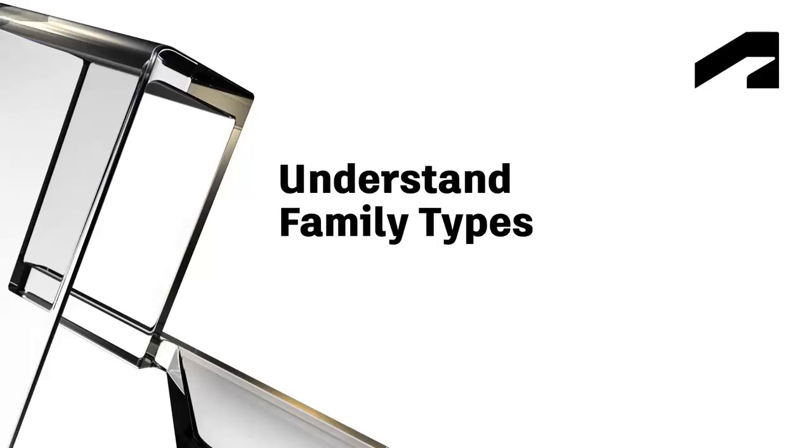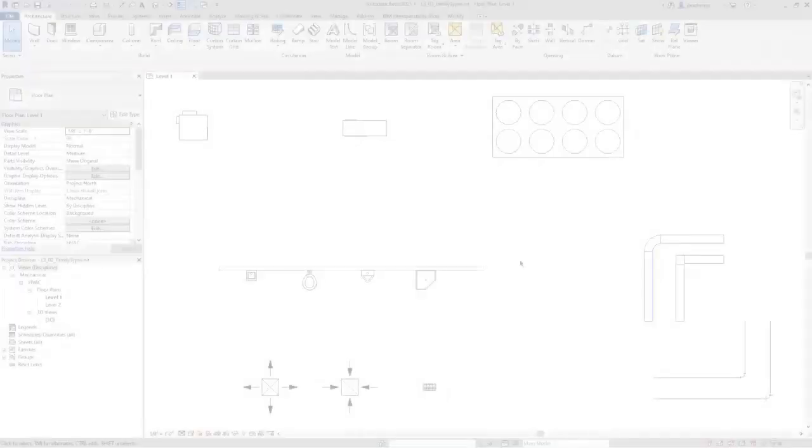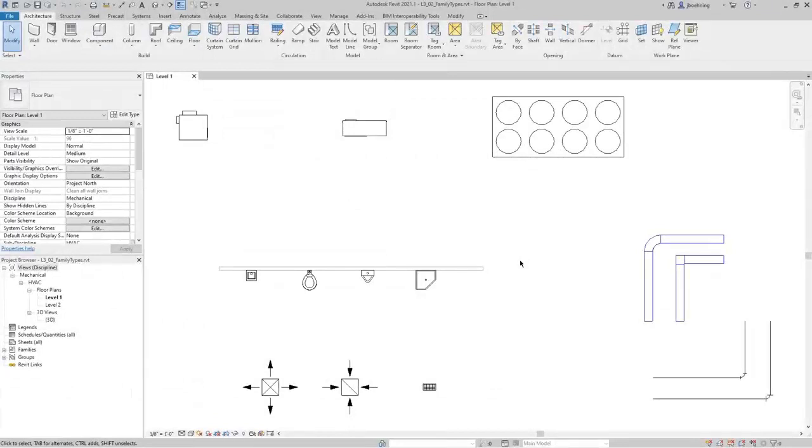In this video, we will cover differentiating between system and component families and editing system and component families. In this project, several elements have been placed. It's important that you understand the difference between system and component families.